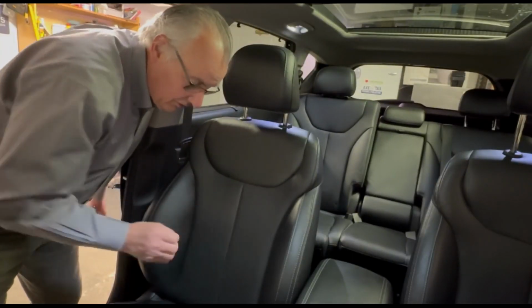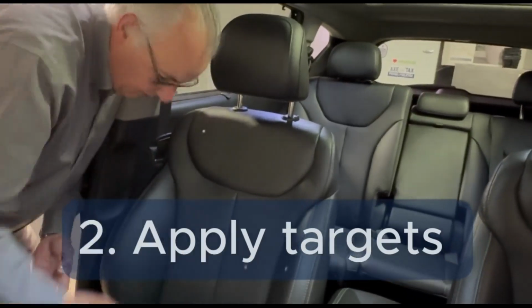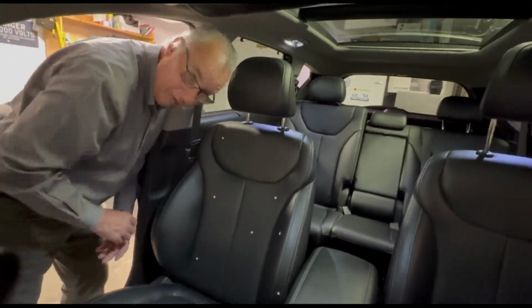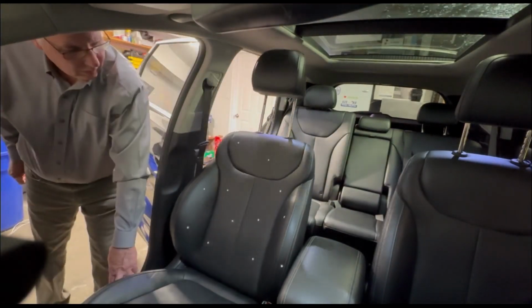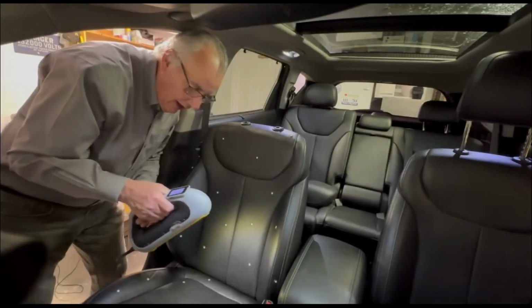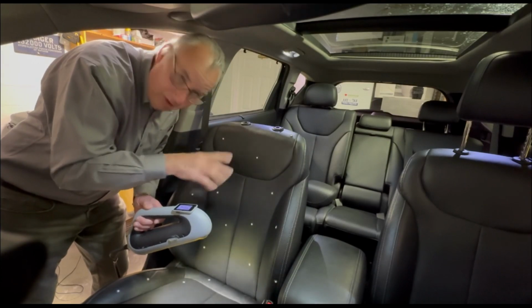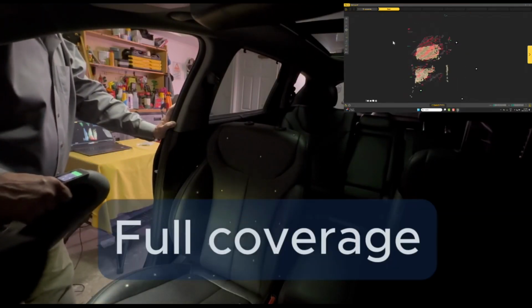Next, you have to set up your physical part and apply targets. The targets help the scanner to pick up the reference geometry in a more reliable way. For this, you have to position the scanner in an appropriate scanning context. And lastly, you scan your part.